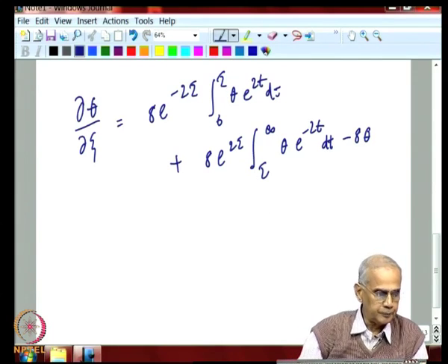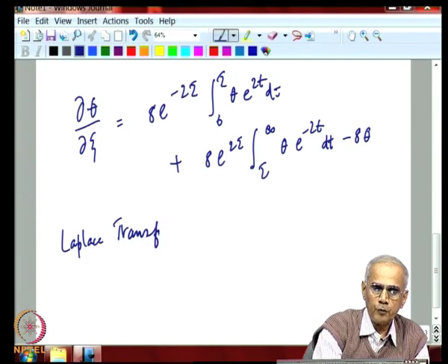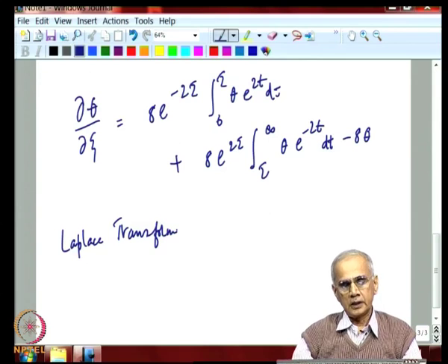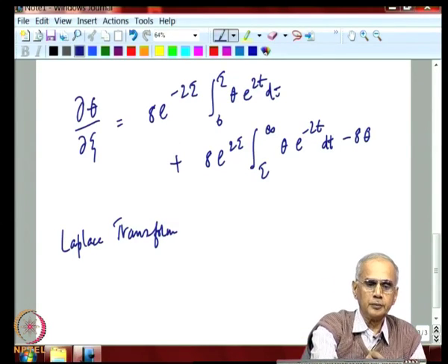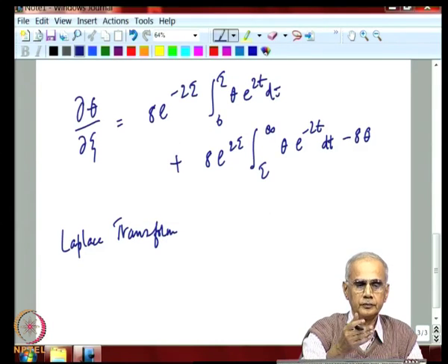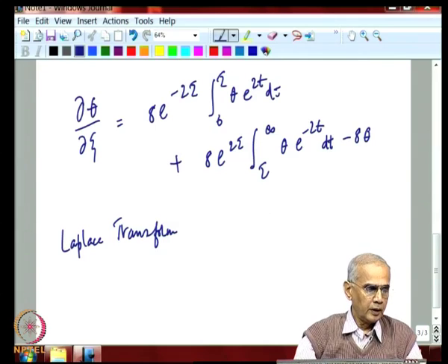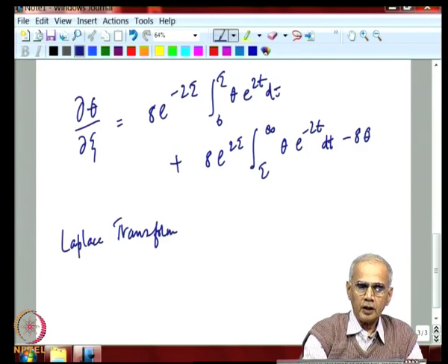Now, to solve the equation, we apply a Laplace transform. Many of you would have used the Laplace transform in transient conduction or convection problems, and the transient term here really is psi, because psi is related to x and u infinity, and it is essentially a virtual time coordinate. Now, the Laplace transform of theta becomes theta bar, a function of s and tau,